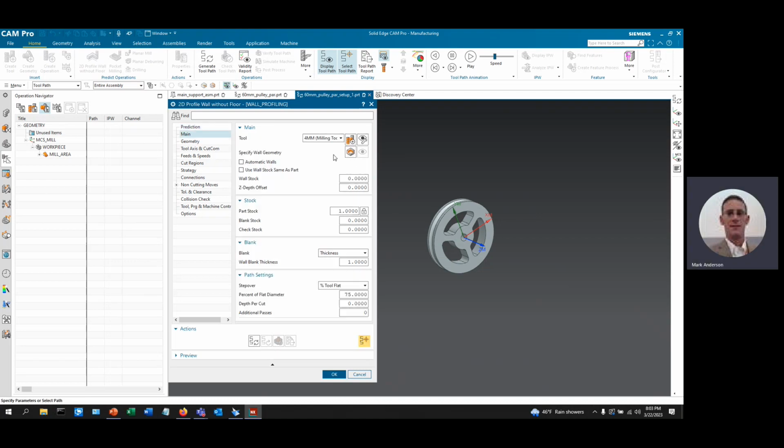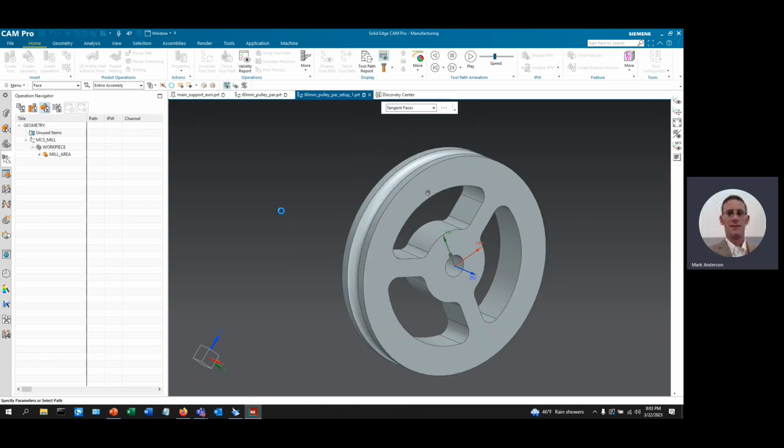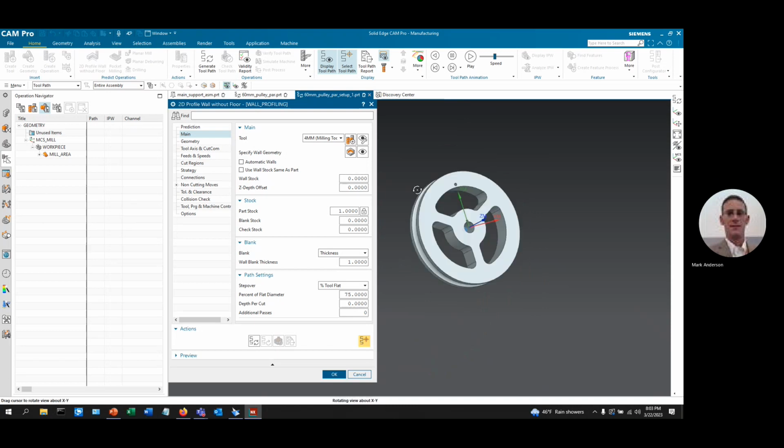So now this operation is asking for our walls. So we'll come through here. We'll have quick settings. We'll select the wall. We're telling it that we want to use that in-process workpiece that I just talked about. And we would like a 2 millimeter depth of cut.